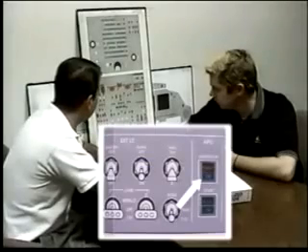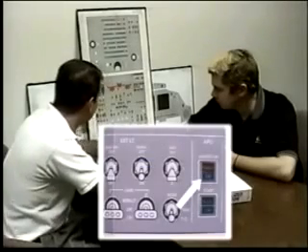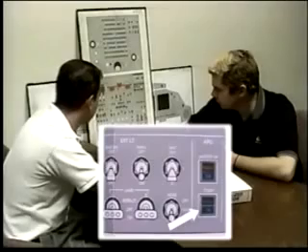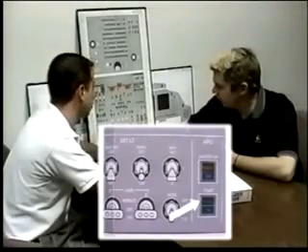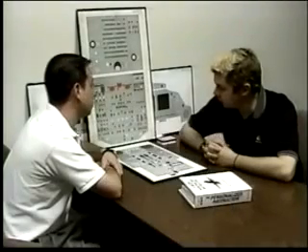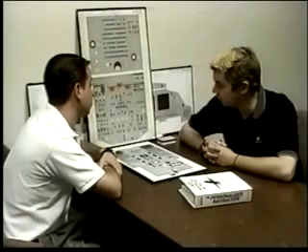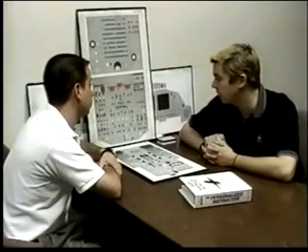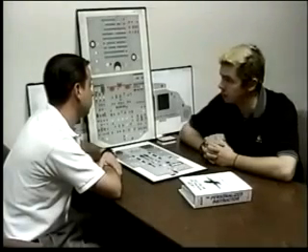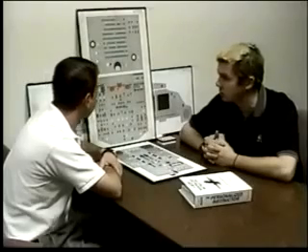APU. You've selected the APU master switch to on, and you selected the start switch to on. When do you get the avail light? The avail light comes on, and the on light goes out at 95% in, and the avail light indicates that either electrics or pneumatics from the APU is available.